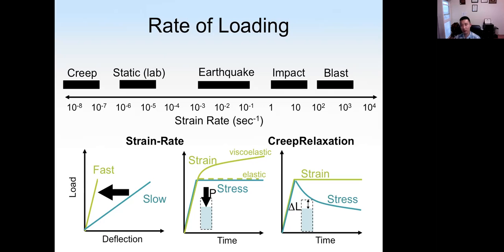So both creep and relaxation occur in concrete, and we can measure how much creep and how much relaxation for the internal stress in concrete. Depending on load level, the deflection will be different. If we apply the same load, the strain will slowly go up. And if you keep the same delta L, the strain level, the internal stress will slowly go down. And we call that relaxation.